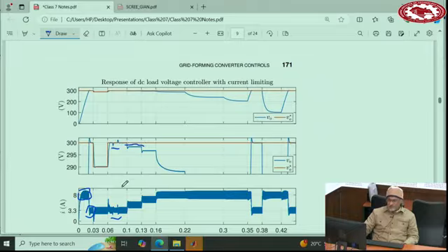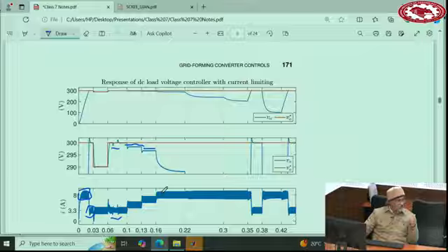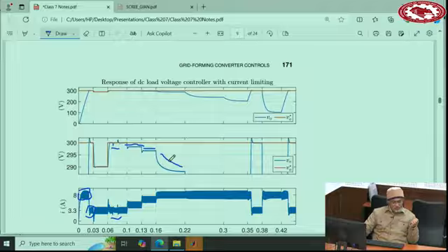See? And then you increase it again, it drops. Now you increase it such that it goes to the current limiting mode, right? So when it goes to current limiting mode, it cannot feed the current that the load requires to keep the voltage. So the voltage drops more. So in that extreme situation, when the load is large but the converter is not allowed to provide that current, the voltage significantly drops, is this one.